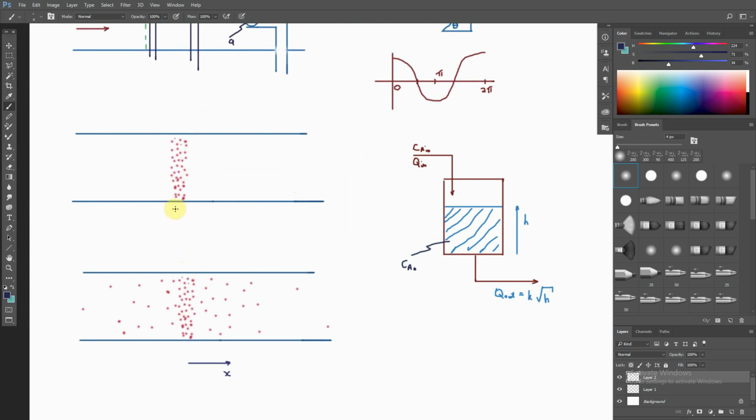And in diffusion, we are claiming that the flux of A is dependent on the difference in concentrations across the space. So here we have a high concentration of A, so Ca at this position, let's call that Ca1, is going to be very different to the concentration here, and call that Ca2, which we can see is 0, right? So there exists a difference in the concentrations here, and if you like, that effectively creates a difference in the electrostatic nature in the fluid. And so we will have, on balance, a transfer of A. So A is in effect attracted to this other region where there isn't so much A around it. So in effect, that's really how we model it. That's how we think of it.